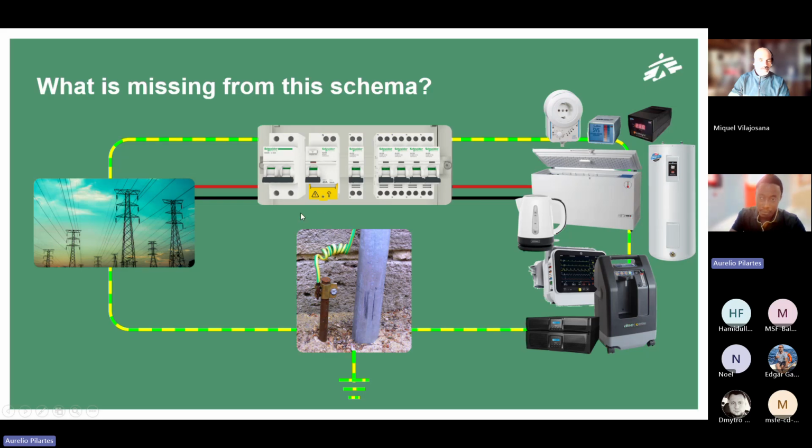And the SPD, which is not materialized here, but it should be put between the main MCB and all the other devices. We have the SPDs to protect against surges. So these ones will protect the installation, and the RCCB will protect people for safety.